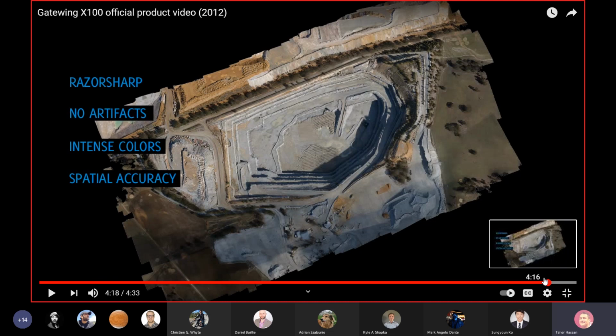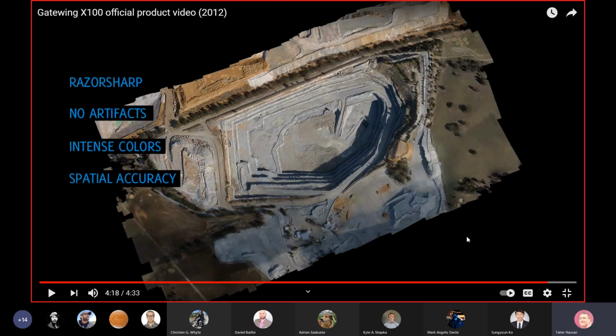Now with a drone, you are completely remote from the surface, and you can still create this fantastic product here. And it also has to do with the speed. Look how long it takes to simply survey this mine. For sure, photogrammetry can do it very fast in terms of data acquisition. So you can repeat the process maybe on a weekly or bi-weekly basis, while before you could do it maybe monthly because it takes more time and more effort.